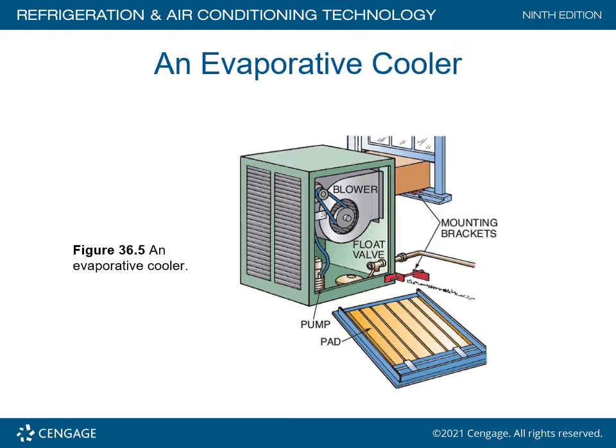One of the problems with swamp coolers is the water quality. If the water quality is really poor, which it usually is, you're going to put minerals on the panels, and eventually you're going to create corrosion. You're going to create all kinds of issues. The way that you can minimize corrosion buildup is on this pump discharge line.